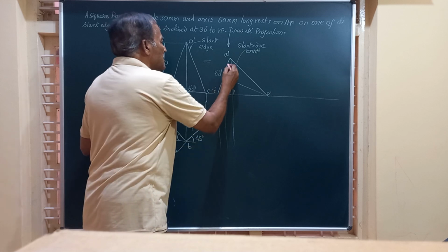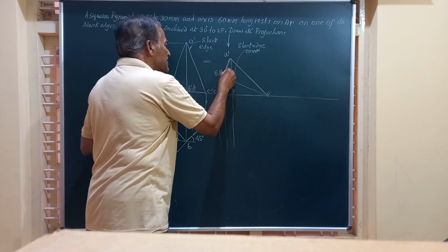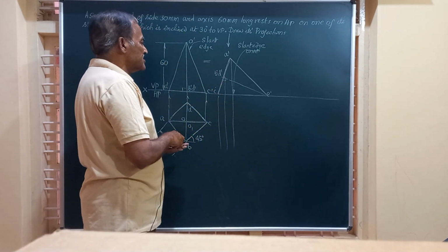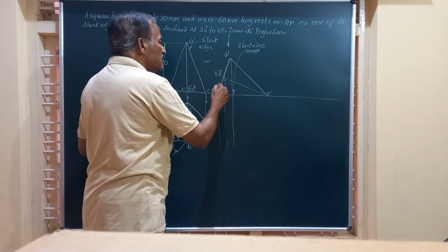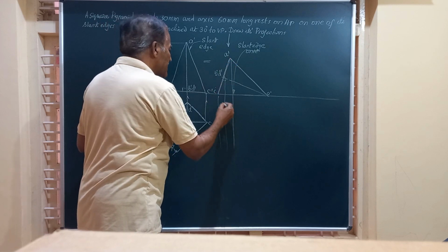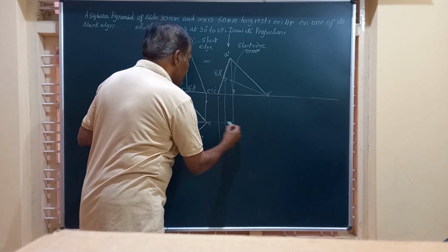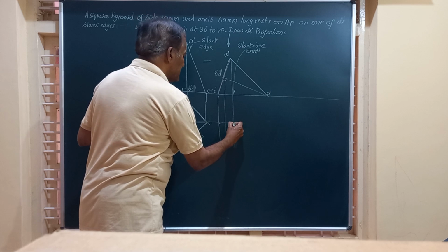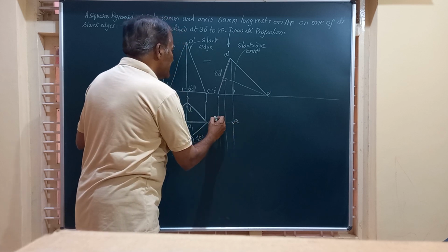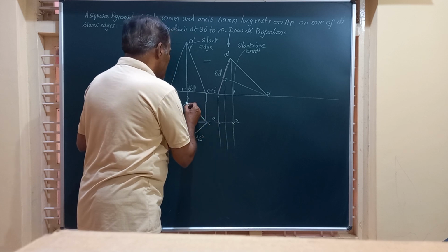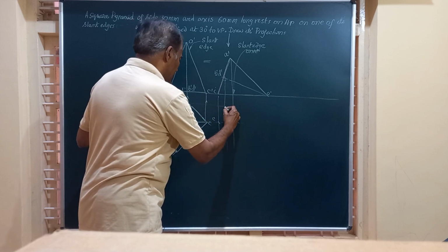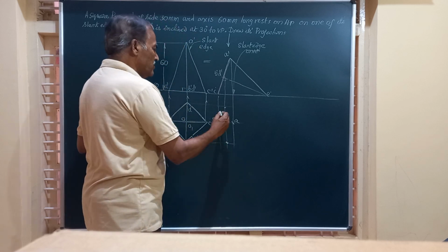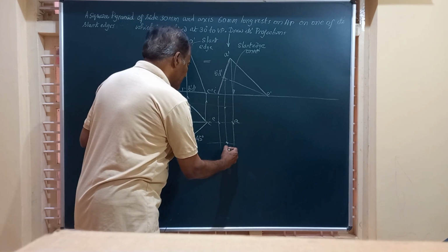of the solid represented by this line here is completely visible in the top view. So what are these? These are the four edges and four corners. Draw a horizontal line from here, and you get this point A here. This comes here. This point is A. Similarly, on the opposite side, you get C, and here you get D, and finally, this point is B. So, friends, we are going to have all the 4 points, namely A, B, C, D.